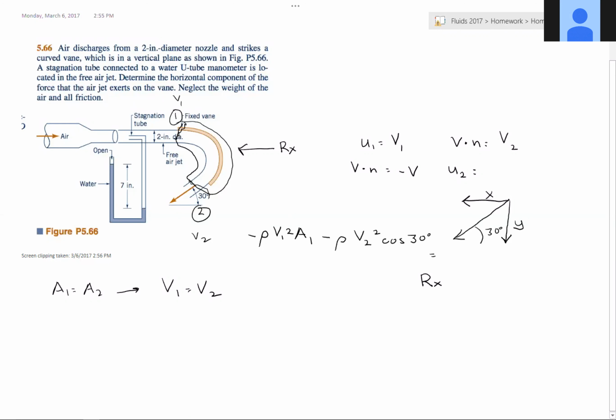That's always the Bernoulli's and the manometer. That's exactly right. So let's go to the manometer to start with. And I'm going to call that 3, because it's area 3. And if you notice, it's part of our problem, but it's not part of our equation here because it's not in the control volume, it's not one of the control surfaces. So what we're doing is we're using 3 so that we can find P1 or P2. So how are we going to find P3?